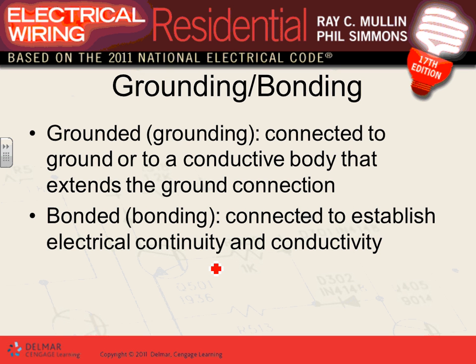in detail. Bonding, you have right above your head. Do you guys see all these suspended ceilings, right? All these metallic. What happens if a hot conductor touches the frame of this metallic suspended ceiling? Could it happen? Look how many fixtures are right above your head. What happens if something like this accidentally happens? Now the whole frame, including this frame, becomes what? Energized.